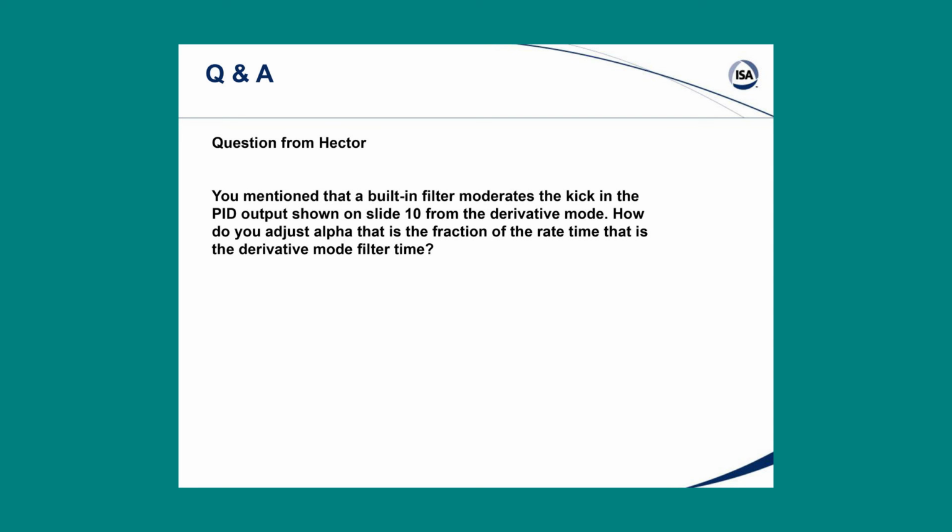That's a good question. In Provox and in many systems, you probably couldn't adjust it. In DeltaV we can, and so should we adjust it? I think if you had a valve with a lot of backlash or stiction, I would consider increasing it, but you would have to be a little bit concerned that if you increase it too much the valve jumps.